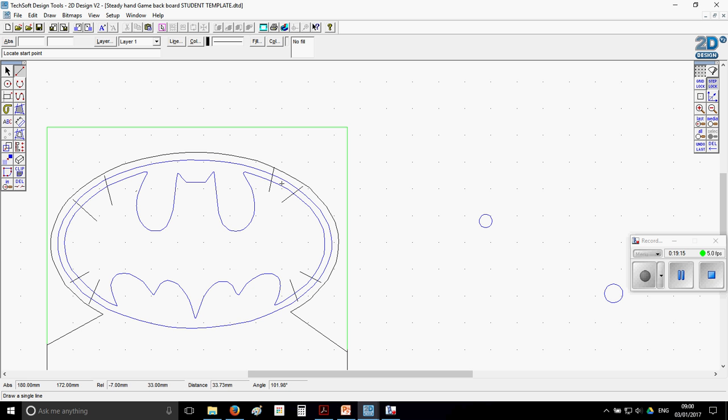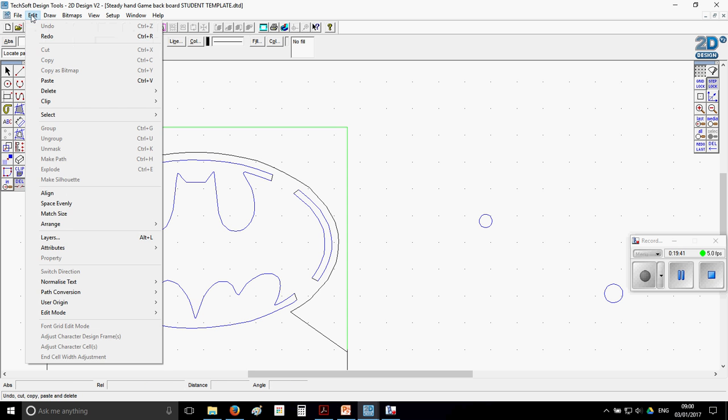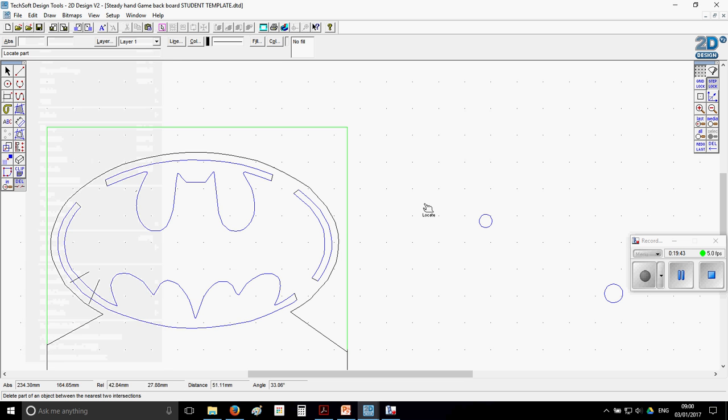and I'll try and laser cut one of these to show you, or that Miss can show you, you'll see what I'm doing. So what I'm going to do is, I've just drawn some weird random lines there. I'm going to get my delete part of the line tool, and I'm going to snip away these bits here where they overlap. You've got to think a bit carefully about which ones you get rid of. Hopefully this is, undo. Be careful, by the way, you only get one undo here. When I do undo, you can go edit, undo, or I'm just hitting Control Z on the keyboard, which is the shortcut for it.